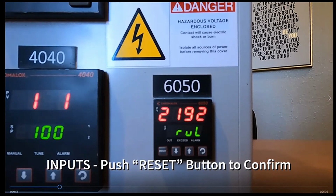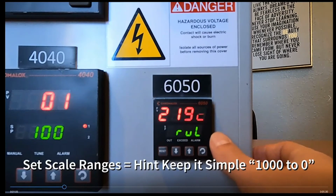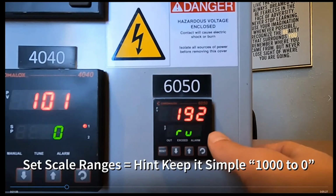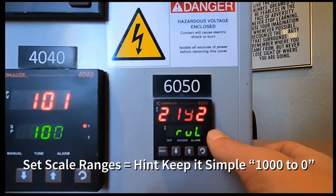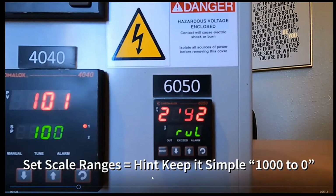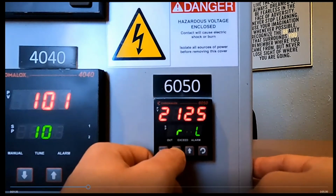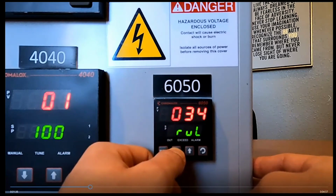So this is what I was talking about before, where it's going to set that range to the sensor type upper limit. We like to keep it simple and bring that back to 1,000. And it's kind of interesting with the 50 series. You should always do the configuration mode first when you're setting up a controller for the first time. But just as a heads up, when you change this to 1,000, it will actually set your upper limit later in the process to 1,000. So if you're wondering why that's happening, that's why. If you hold in the button, it starts to skip through numbers and goes a lot faster, as you can see, versus just clicking it one at a time.